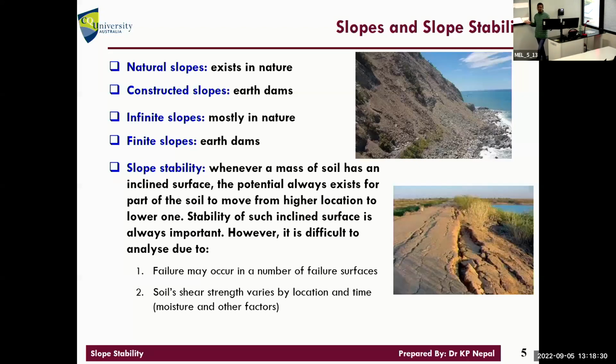What is slope stability? Whether the soil will be there or not, right? Whether it moves or it stays in the same place. If the slope is very steep, mostly it falls, yeah? But it depends on the soil. If it is rock, it does not that much. But if it is clay, it just goes out, yeah? Let's check some of those. Look at here. The top picture is what? Natural slope. The bottom one, we constructed it, embankment.